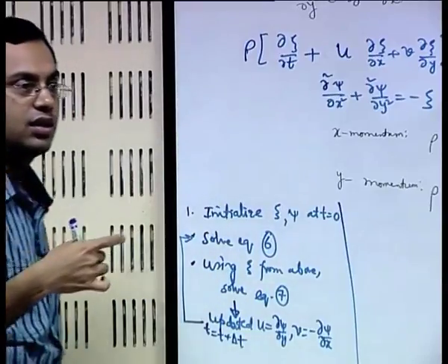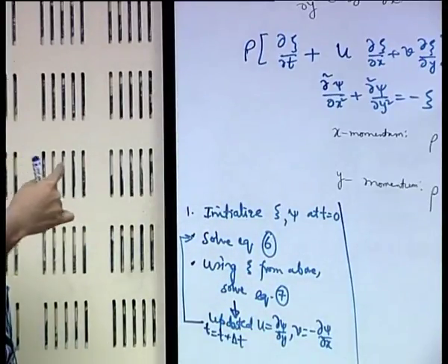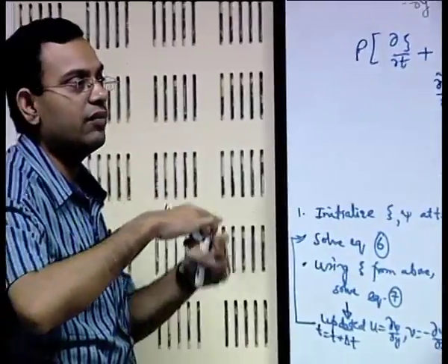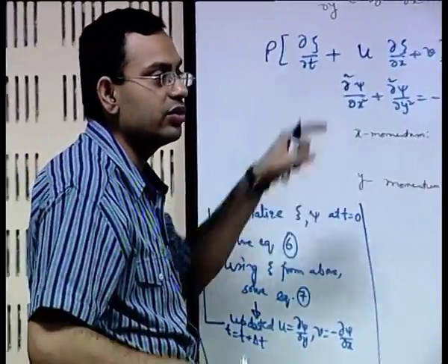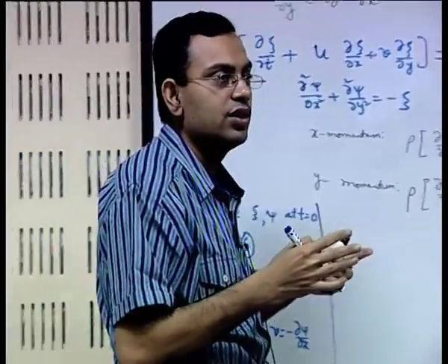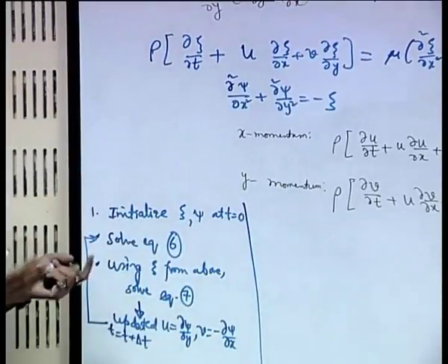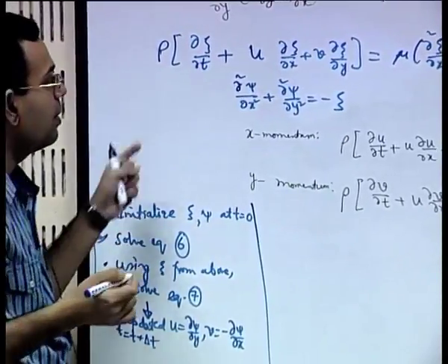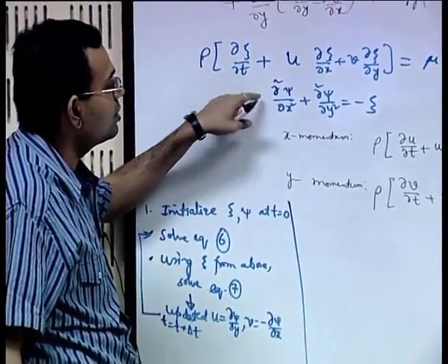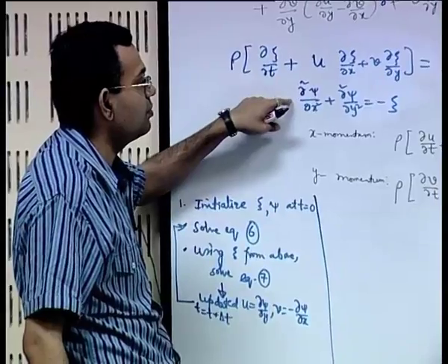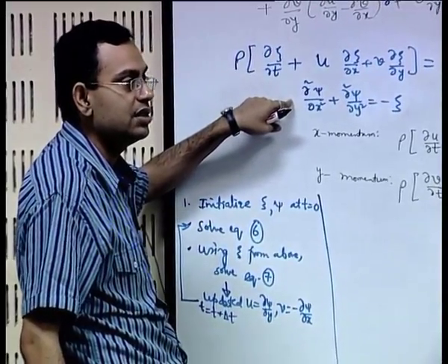That is how you can march in the outer iteration with time, and in the inner iteration this is like an elliptic equation. So it is not a marching problem, so you have to solve by any of the iterative schemes or elimination schemes, whatever is convenient, but you cannot march in time for this equation because this is not a marching type of problem.